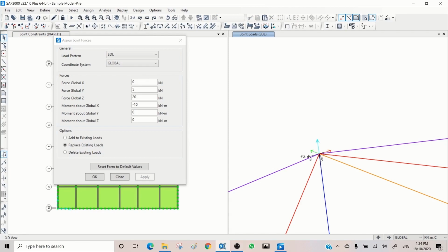Actually this arrow is addressing your thumb, based on right hand rules. So if you keep your thumb aligned with this arrow, you can see the right hand rule works, and it shows where the moment direction is exactly. And the same for loads. If I change, for example, Z to -20, and then here I replace it, you can see it's coming back.